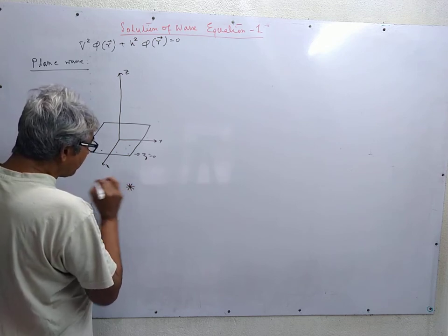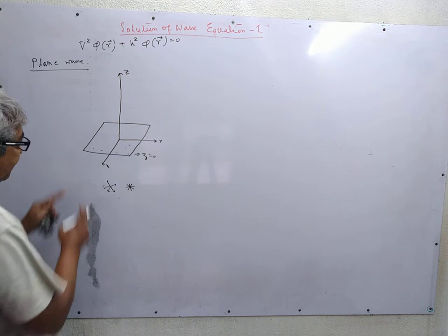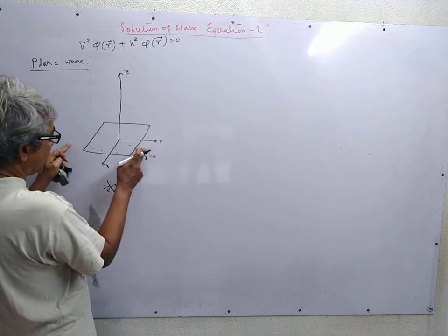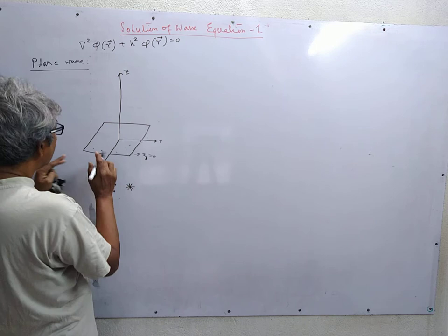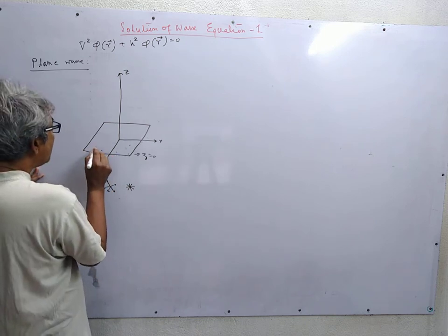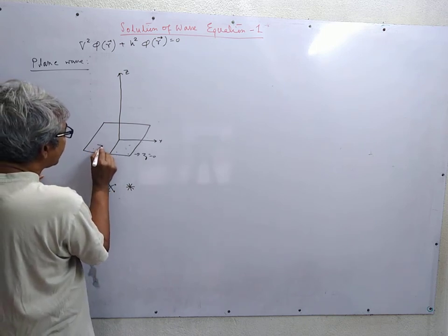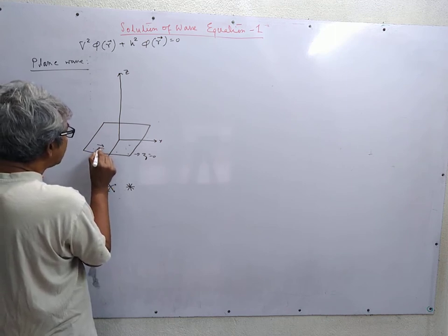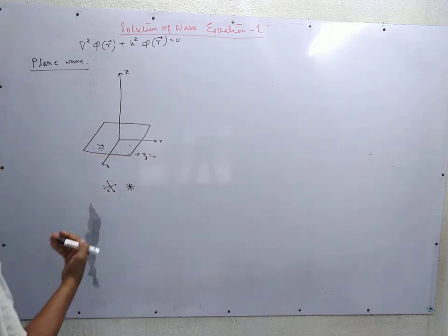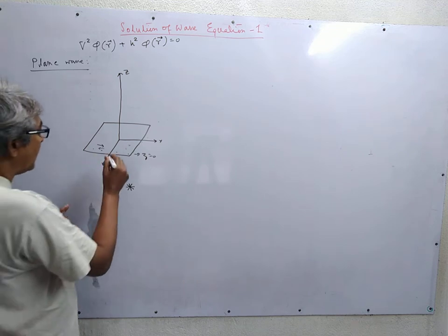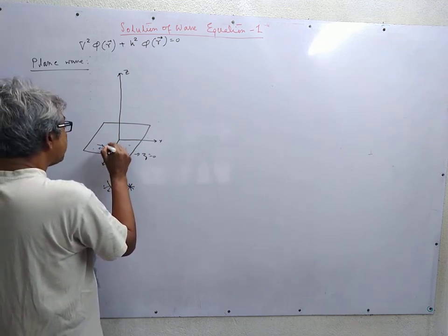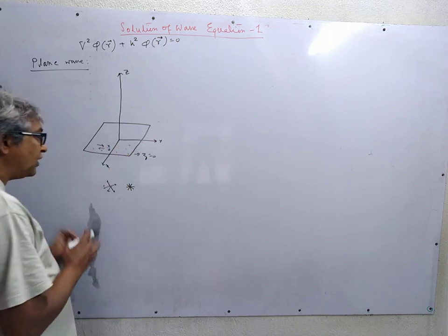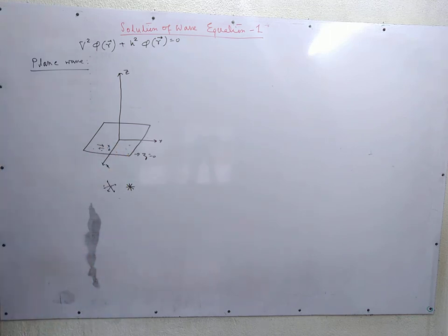We will have propagation in all possible directions. If we consider the points not near the end or edges of the strip, then the amount of energy flowing laterally to the right is exactly equal to the amount of energy flowing laterally to the left, and this is the same for the positive x direction and negative x direction. So overall, except near the edges of the plate, there is no lateral flow of energy, and all the energy flows along the z direction.